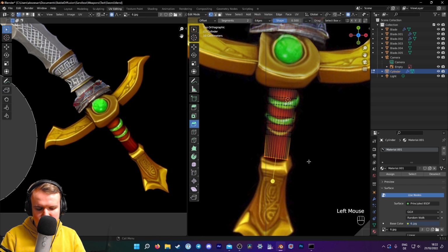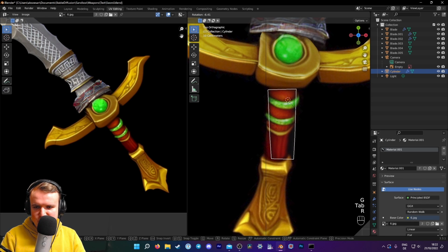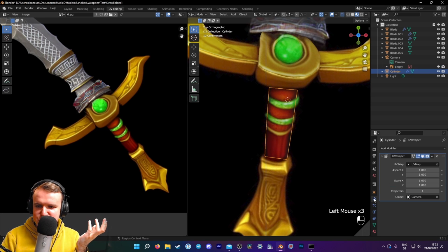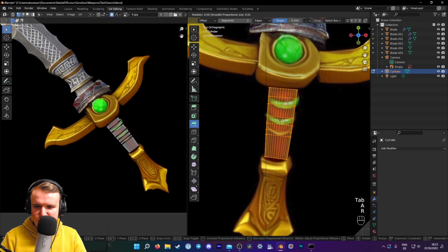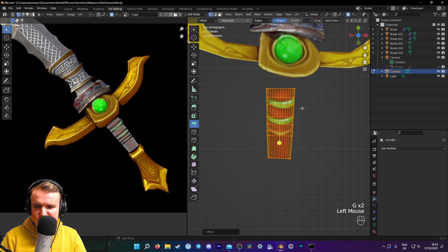And now there's one thing I'm noticing, right? So as you can probably tell as well, this is going to be a perspective issue too. I have to switch into projection now. So I'm going to apply my UV project, go into edit mode, and first I'm going to make sure my rotation is normal again, because this reference is getting kind of crooked now. So I'm going to hide that again.